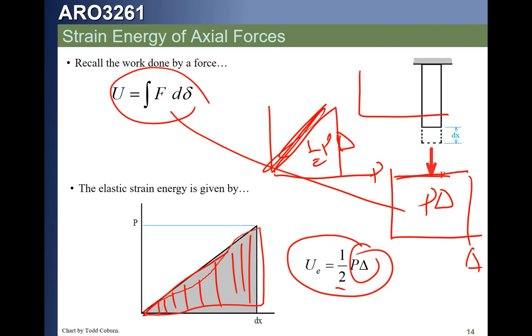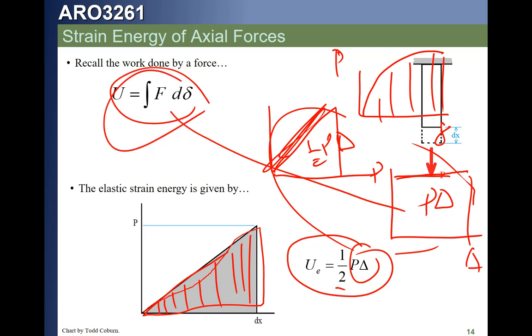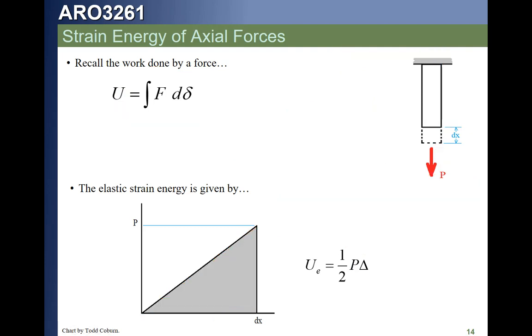If we had a load deflection curve, P versus deflection, that looks something like this, it's going to be something between these. It's whatever the area is under this. We'd have to integrate that puppy, right? But if we're talking about the elastic strain energy, we'll see this 1/2 P delta. We're just going to hurl a 1/2 at it. A lot of books will do that without really explaining it. The reason is because they're talking about the area under that curve and you're down in the elastic range. Got that?